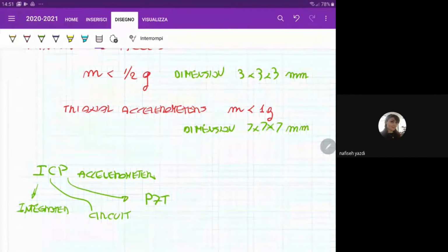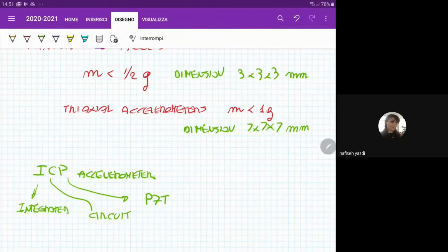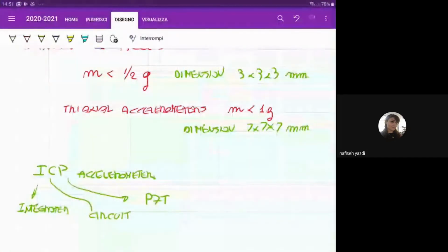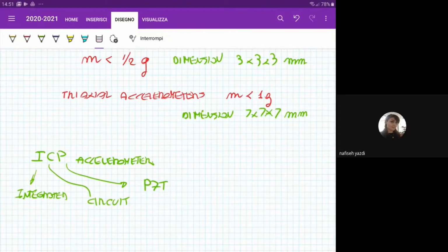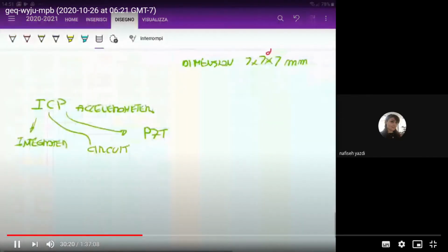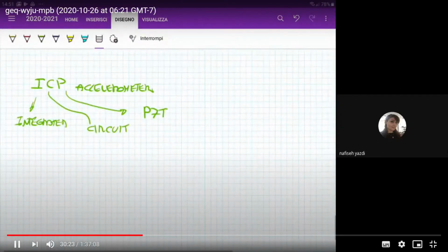And they having such a characteristic. Of course, you pay the cost of having less accuracy with respect to the charge accelerometers, because the charge accelerometers have, let's say, the maximum sensitivity, the highest accuracy. The ICP-based accelerometers are in fact very useful, very handy, and they are not that accurate as the other one, but we can use that every time. In the laboratory, we are using those accelerometers. Let's see now two configurations.